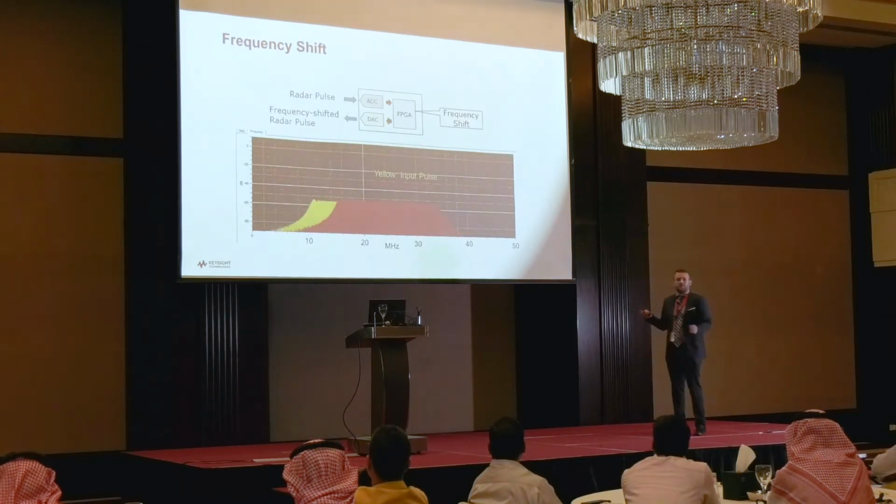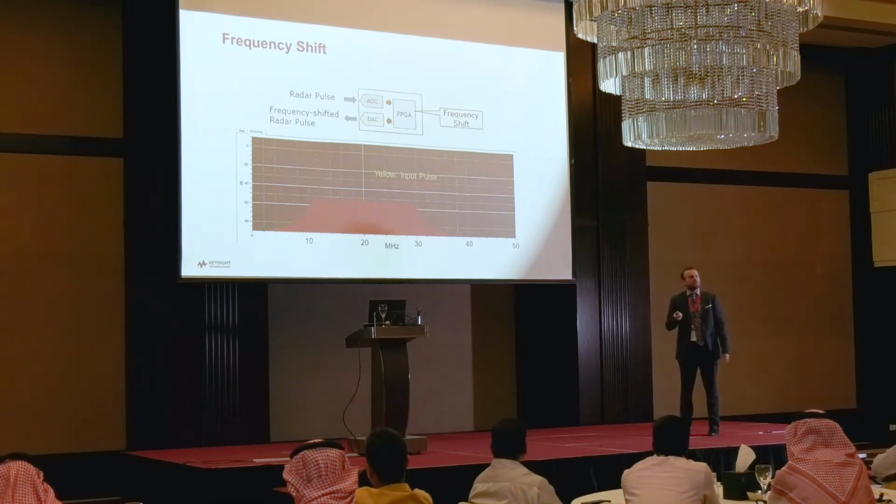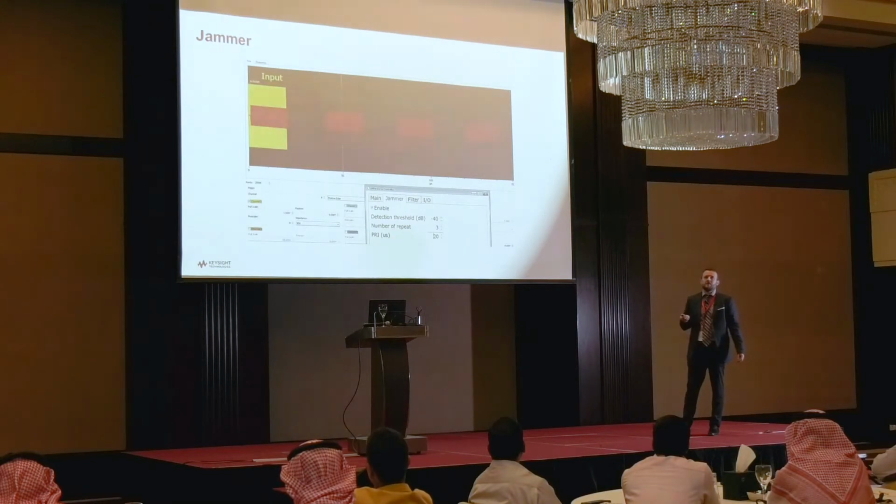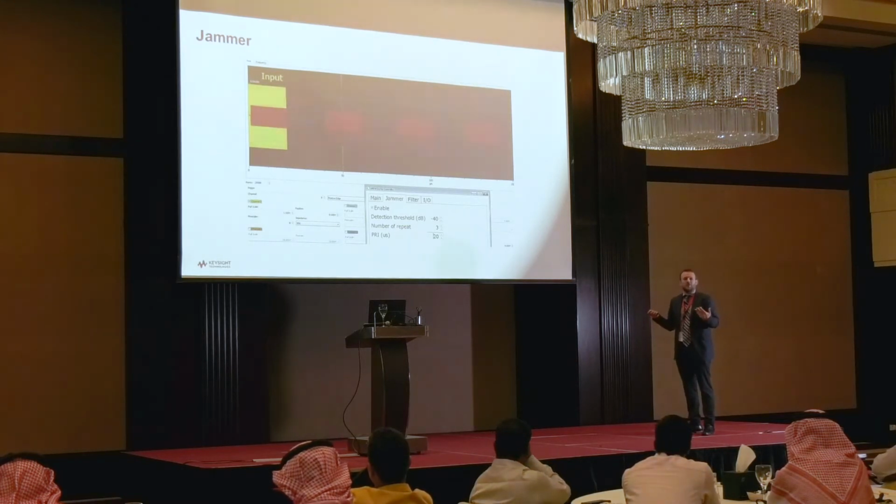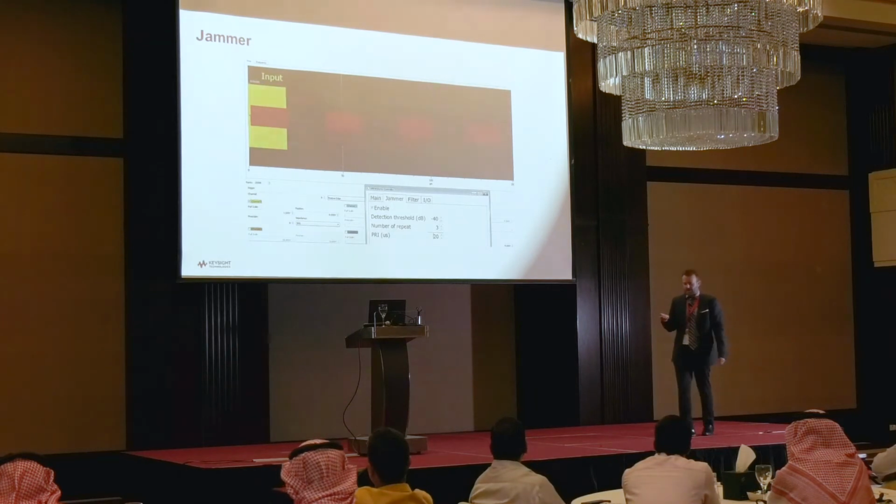Similarly, we can capture that pulse and shift it in the frequency domain, and this is using single sideband modulation, so we can simulate a Doppler shift with a very simple frequency shift of that pulse. And here we can see the enabling of a jamming signal, so we're repeating that pulse multiple times, and that can be controlled programmatically.